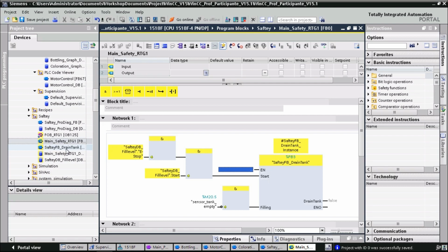You can also switch to the alarm view control and to the screen in which it is located, and you can also switch or show the S7 graph in your PLC code viewer. What you can also see in the control, in the right upper corner, is the initial step, if that one is active, or if it is a parallel step which is active right now.